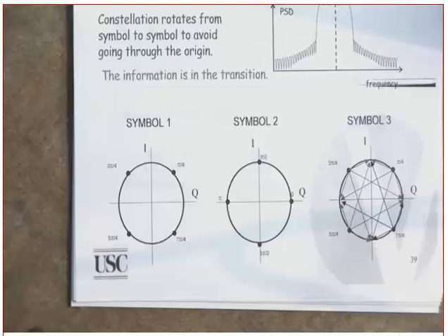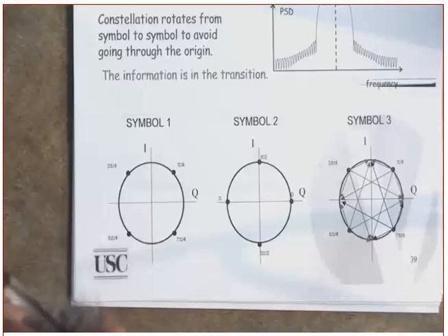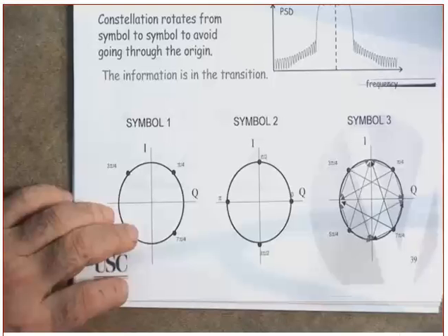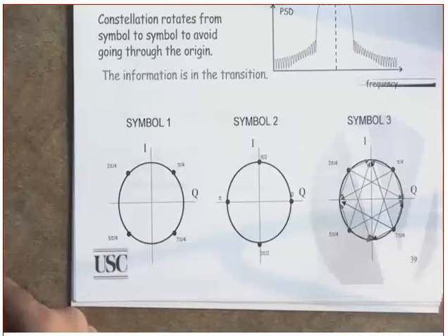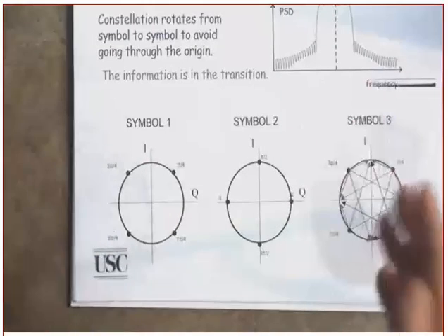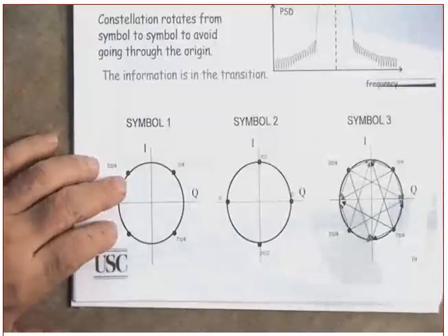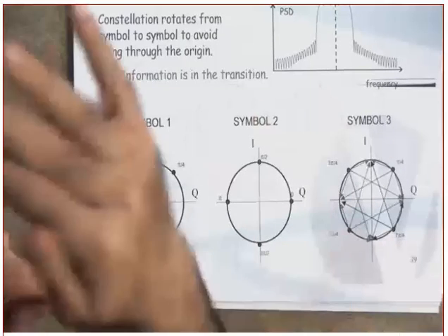No, you are not getting it. Say that again. You tell me. That's a good question. The question is, if you do have the same symbols, in other words, 1, 1, the next one is also 1, 1, 1, 1, how does the signal look like? After you demodulate, what are you getting? Before sampling, you will get a straight line, which means it is harder on the receiver to synchronize its clock, not the carrier.